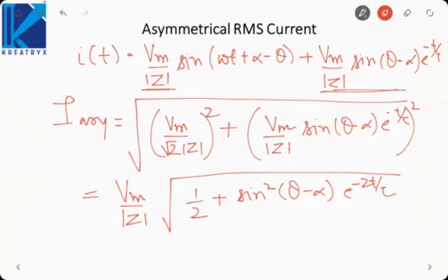If fault current is allowed to persist for such a long duration, it can lead to system damage because high current flowing for a long duration will cause overheating of the system. That means we have to operate in the transient region. So circuit breakers are always opened in the transient region, not in the subtransient or steady state.